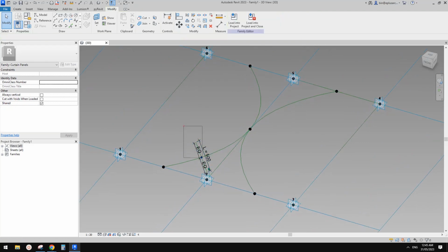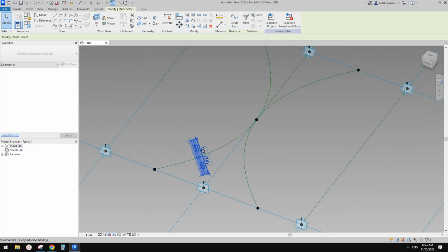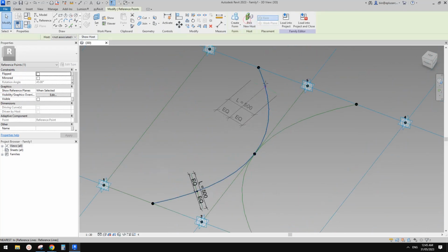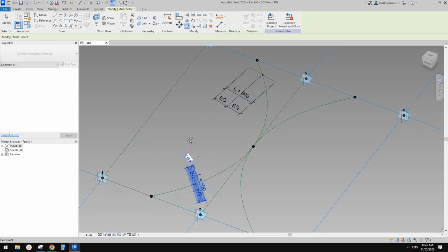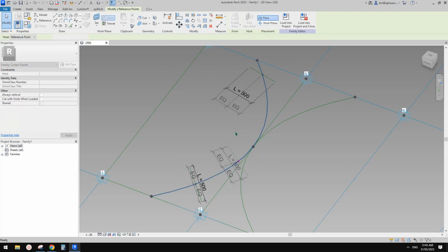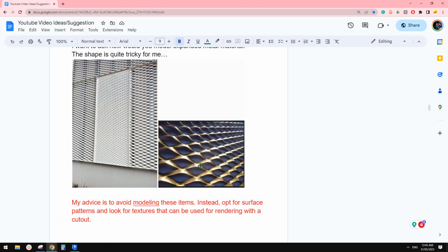Okay. So then we can copy this. Copy everything here. Okay. So this line, the point, dimension, parameters, Ctrl+C, and select the point and pick new host. I'll just place it roughly there, and also I'll just copy this again and place it in the middle roughly. Okay, so the reason why we need 3 profiles is, if I go here,